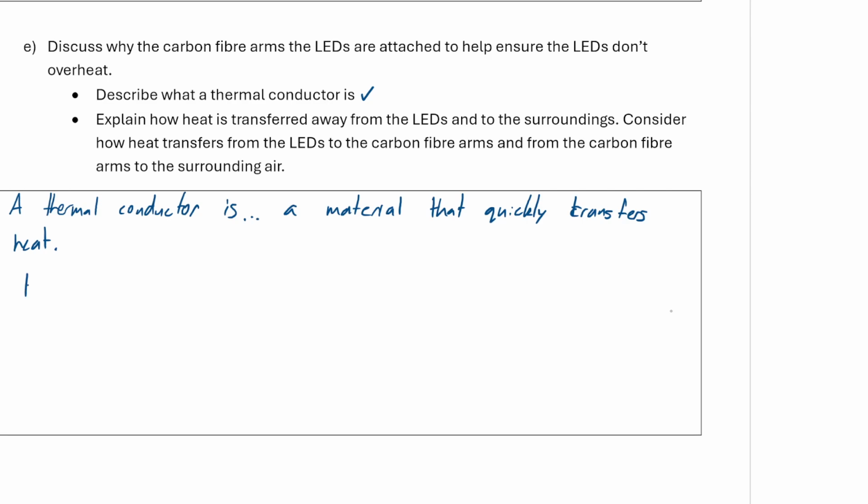So the hot LEDs transfer heat to carbon fiber arms, and what heat mechanism is it? Is it conduction, radiation, convection? Since they're touching, right, they're making contact, it is through conduction.